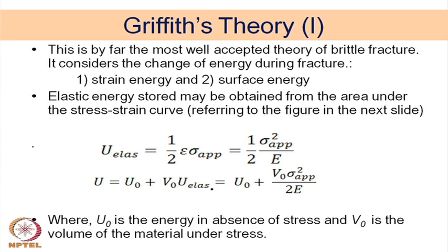So, there is an extension of the bond length. The distance between the atoms is increasing, even if they are still attached to each other, but there will be a strain energy generated inside. Only when the cohesive energy is broken, the bond is broken, then you have a surface energy term as well. So, the elastic energy stored may be obtained from the area under the stress strain curve, referring to the figure in the next slide.